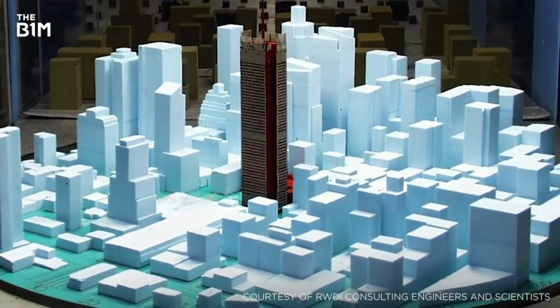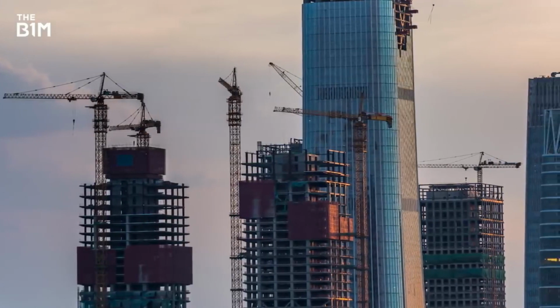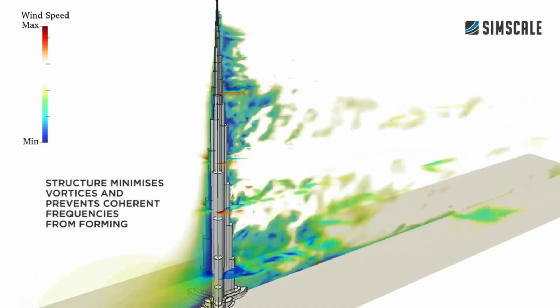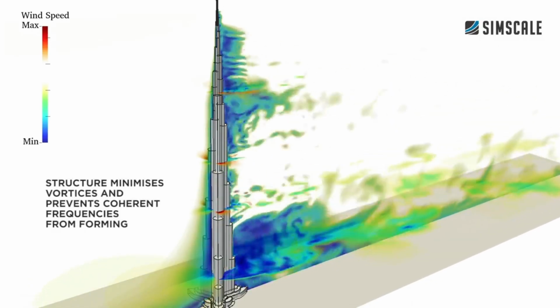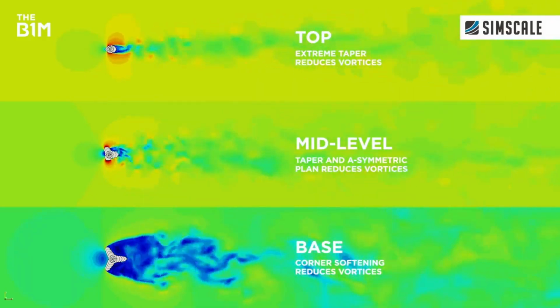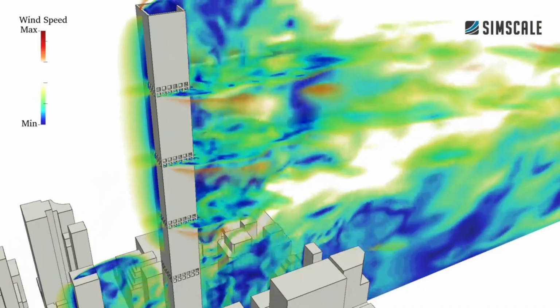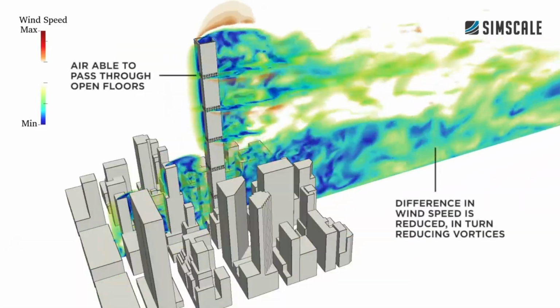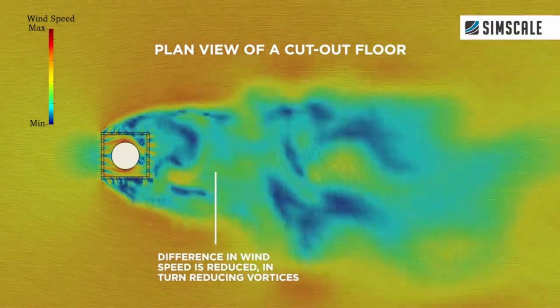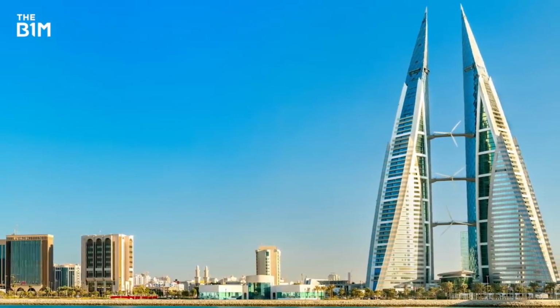The speed of potential winds, the height of the building, proximity to water, and proximity to other structures are critical factors in the analysis. They also consult historical records and building codes to determine the support and strengthening required for a project. Using predictive models, structural engineers can anticipate potential challenges and prevent life-threatening situations posed by high winds.